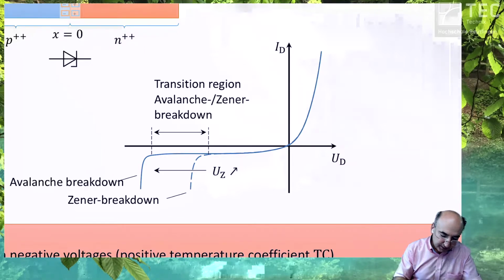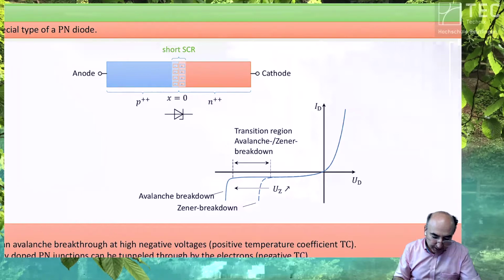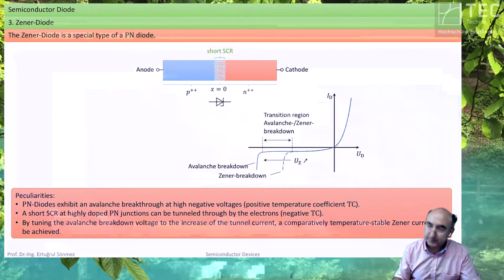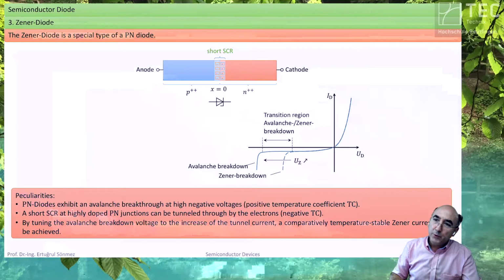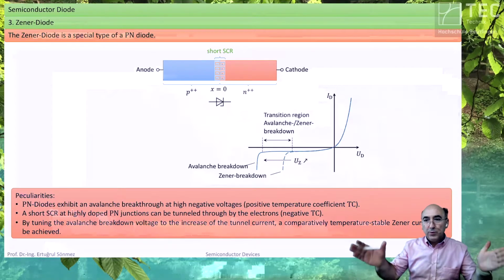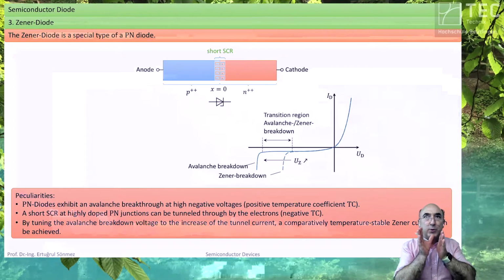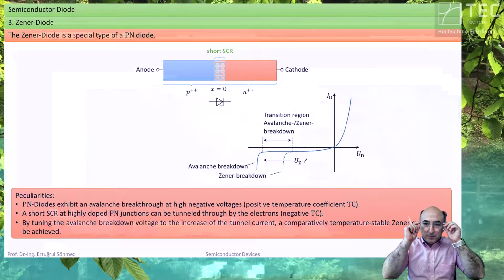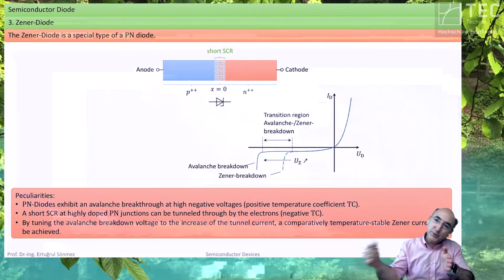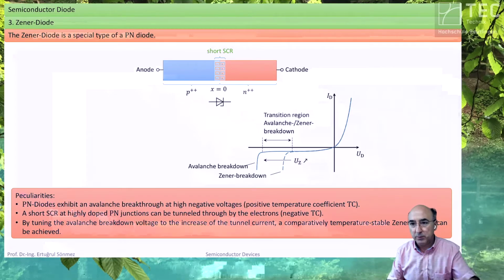The second effect in the Zener diode is, you know that you can go through the wall without making a hole into the wall. You can tunnel through the wall if you are so small like an electron, and if the wall's extension is comparable to the wavelength of the electron. So that's the tunneling effect. If you are small and the wall is thin enough, you can tunnel through the wall, the potential wall.